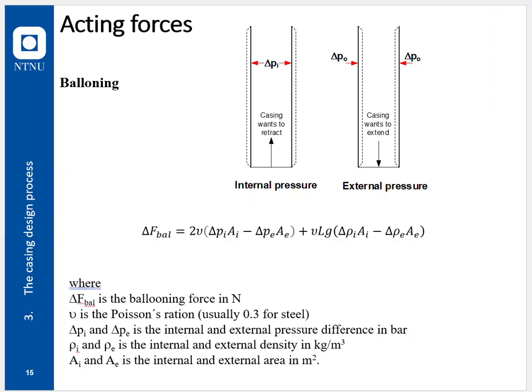Ballooning always seems to give an added tension in the pipe that it is acting on, regardless of whether you're pressuring up internally or externally. I hope and think that the drawing on this slide is visualizing the situation and the cause of the origin of the ballooning, so that I don't need to explain that too much.